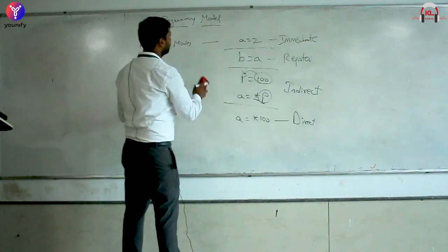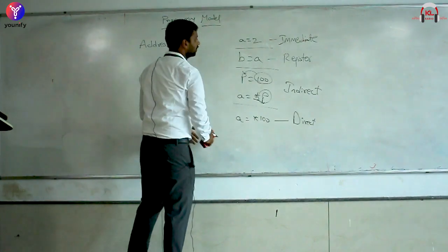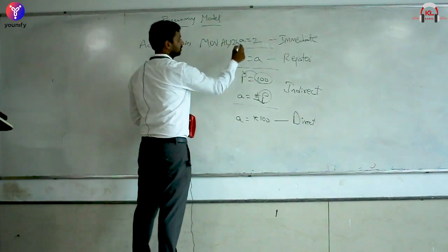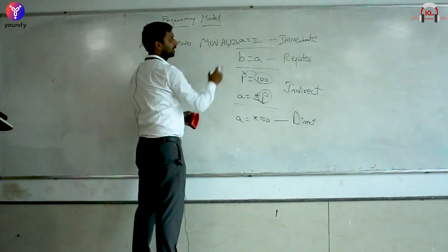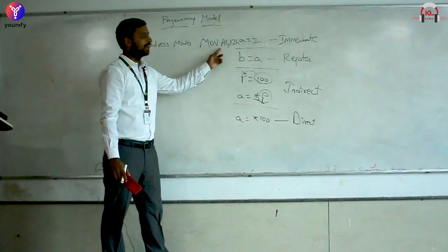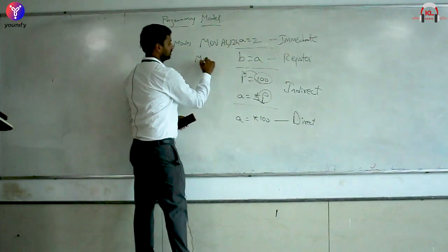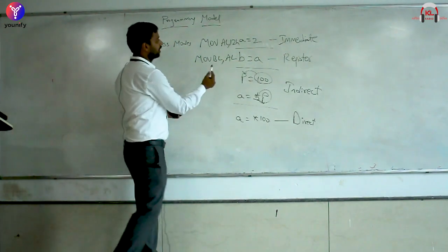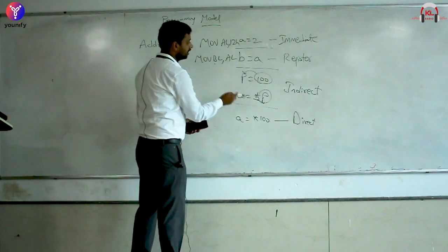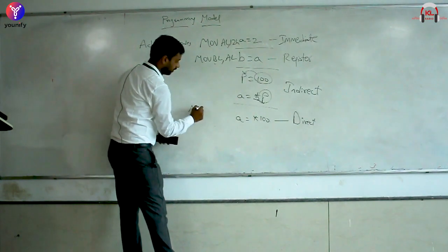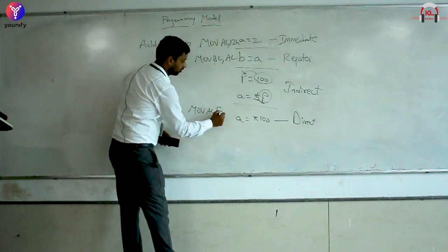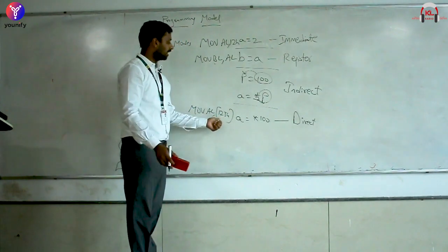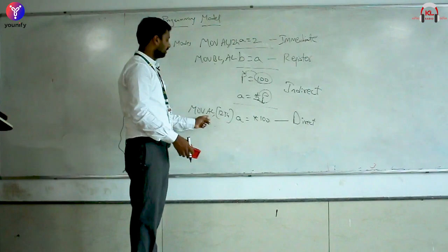If we classify them or write an equivalent example of everything, this will be MOV AL, 12H. So if you are assigning this, we have an immediate value assigning to a register. The example would be MOV BL, AL. Here we are interacting between 2 different registers. The direct would be MOV AL, 1234. Why 1234? The size of the address happens to be 16 bits. And this is how you get your data.